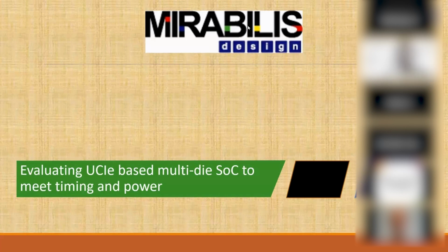This was a question with regards to UCIe. So to answer this question, VisualSim Architect has created this UCIe 1.0 based on the UCIe standard. So all the standard components that are there in the standard have been incorporated into the UCIe model in VisualSim. So all the data flows, all the controls, the sideband, the main band, all of those have been incorporated into the implementation. So when you get the UCIe library, you actually get all of these components within the single package.